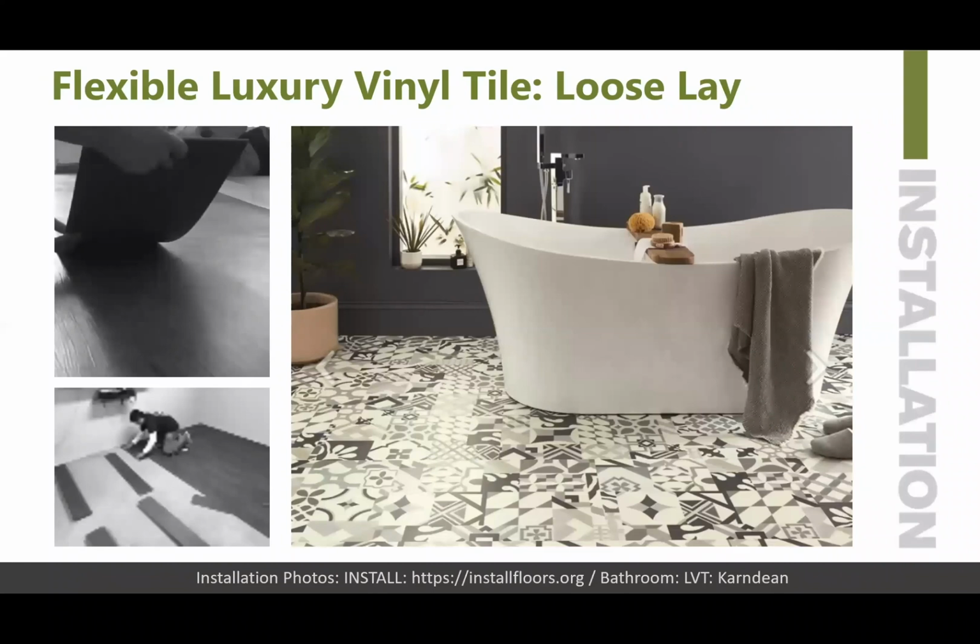For loose lay, flexible luxury vinyl tile can be installed over existing floor coverings, which is one of the advantages as well. Vinyl flooring adhered to the edges of a subfloor, then additional planks and tiles are typically laid in place without an adhesive. Loose lay can easily be removed and replaced. This makes loose lay tile an ideal option for areas where flooring may be temporary or have a short lifespan. It allows you to do the replacements and will not damage the substrate, but also the flooring product.